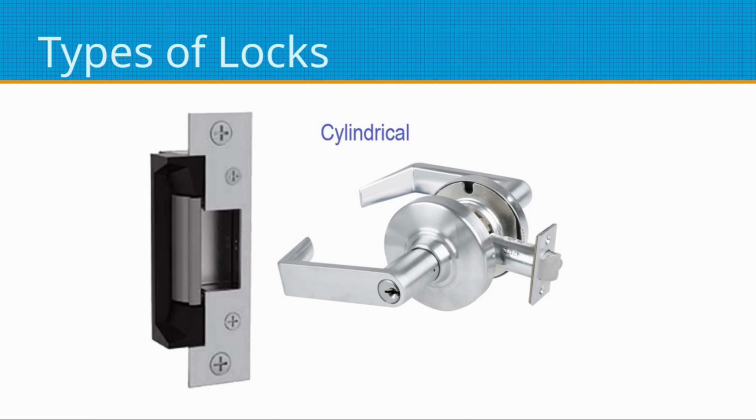It's the same concept as the mortise lock. The latch drops into that pocket. When you electrify the strike, the gate comes free and you can pull the door open, or if you turn the lever on the inside, then you can retract the latch and go out.